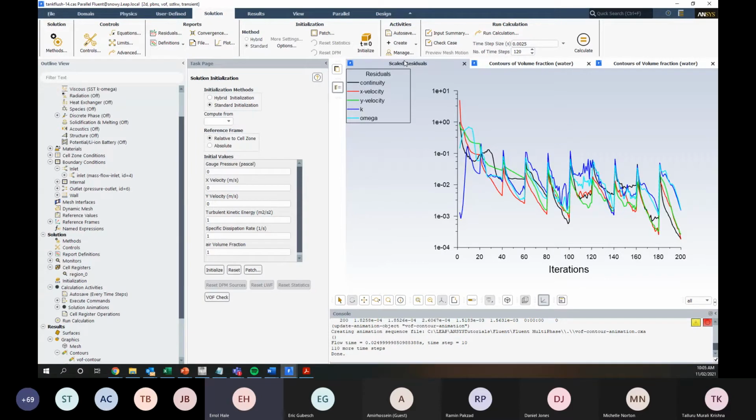And to be honest, we don't really want to have any more than 3 or 4 iterations per time step. So for a really well-defined model, something that has good convergence behavior, we're expecting about 2 or 3 iterations per time step. Remember, in a steady state case, we might have to solve for 1,000 or 2,000 iterations to get a converged solution. When we're doing a transient case, it doesn't require as many iterations per time step, but obviously you're solving for a lot of time steps generally because you need quite small numbers in order to get good convergence behavior.